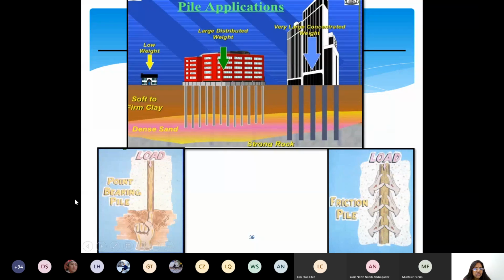So it's another picture illustration of how the end-bearing pile is acting. It's just at the end only, at the tip only. Load is distributed at this point, and these sides will not take the load. And here, see, it is as though the resistance is offered by many hands on the sides, frictional piles, as though many hands are supporting on the sides due to frictional resistance. Friction means what? Resistance offered to movement, right? So the pile will not move due to the load coming in, due to the strength of the friction provided by the material of the pile.